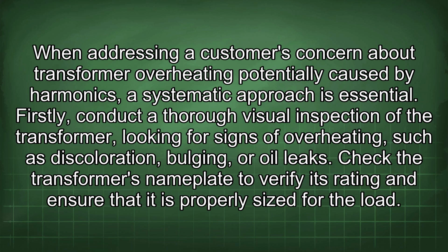When addressing a customer's concern about transformer overheating potentially caused by harmonics, a systematic approach is essential. Firstly, conduct a thorough visual inspection of the transformer, looking for signs of overheating, such as discoloration, bulging, or oil leaks.